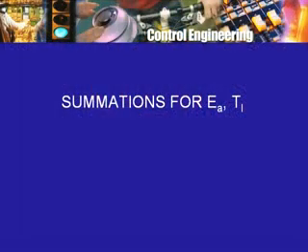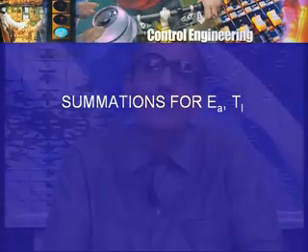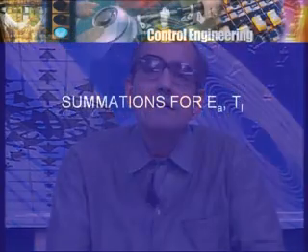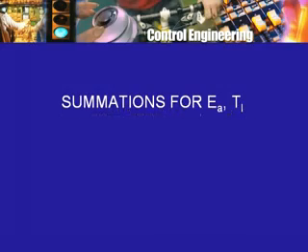So, I can have a signal flow graph in which there is a summation corresponding to the node EA, and that is of course very simple. EA equal to KB into omega m plus RA into IA. So, it is quite easy to represent that by an equation. The other equation is the torque equation, from which I can get TL, the load torque, equal to KT IA minus KF omega m, and so that is also very easy to represent.